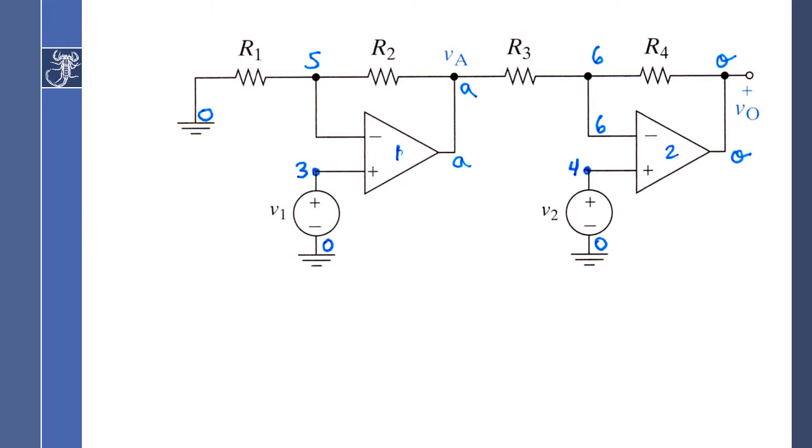And if we want to use those as values for the sources, it would be confusing to have a node name, for example, 1, because then V1, does it refer to the value in the source? Does it refer to the voltage? So we have to be careful not to have a node 1 if we are going to use V1 as a constant.